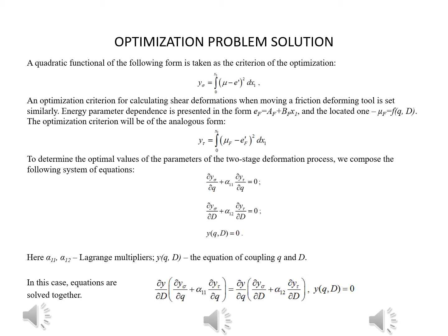To reduce wear, it is necessary to reduce the value of the coefficient of friction, and increase the hardness of the material, the temporary resistance to fracture, and the relative elongation of the material of the part. The minimum value of the coefficient of friction is reached at a certain value when sigma_n is equal to sigma_0n. Its value is largely determined by the operating conditions and the geometry of the part. The relation has no extremum by sigma_b and delta.